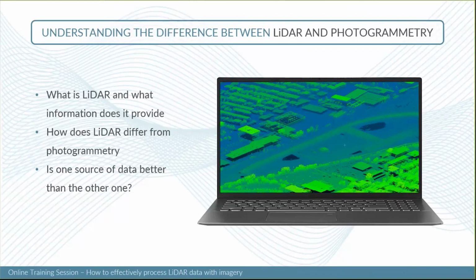Another advantage with LiDAR is that it could be flown day and night, since it's an active remote sensing technique. It doesn't need an exterior source of light to be used. It sends its own energy and then collects it back from the sources. And also, there's no geometry distortion, or less than what we have with photogrammetry, and so that's another advantage.